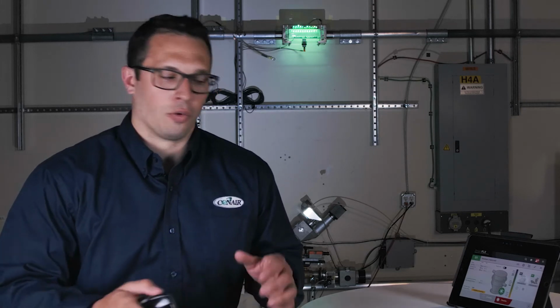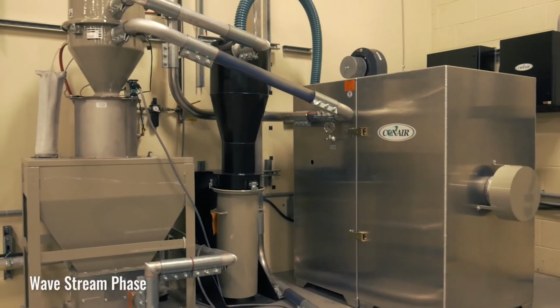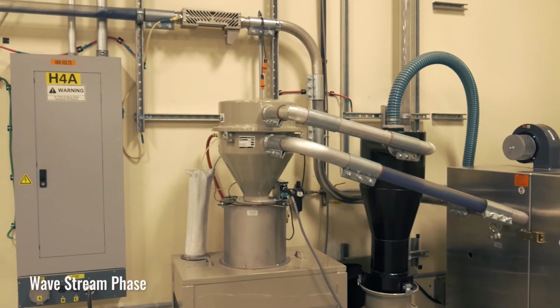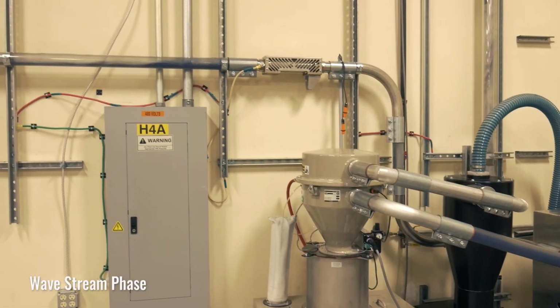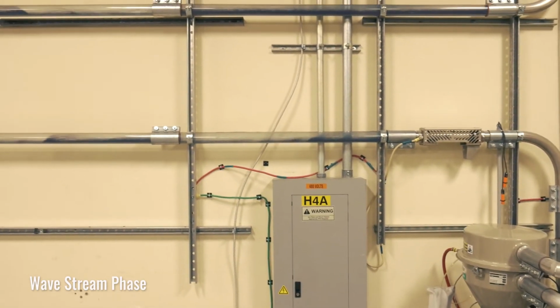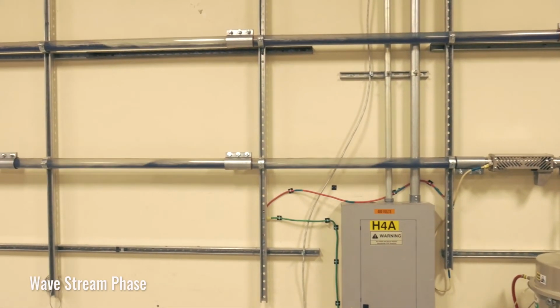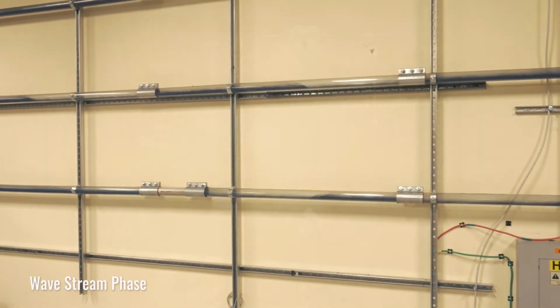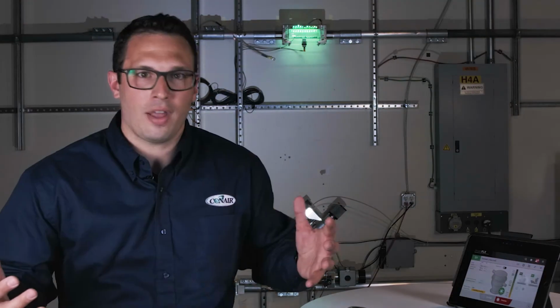Now, dilute phase requires a continuous high pickup velocity. The reason is you have to continue to pick up resin into your material handling system while holding true to an industry standard of 3,500 to 4,000 feet per minute of pickup velocity. That is required because resin is sitting in its bulk storage state. If it's in a silo, a surge bin, or a gaylord, however that resin gets to your facility, it's sitting there and it's not moving. Its velocity is 0, quite frankly.